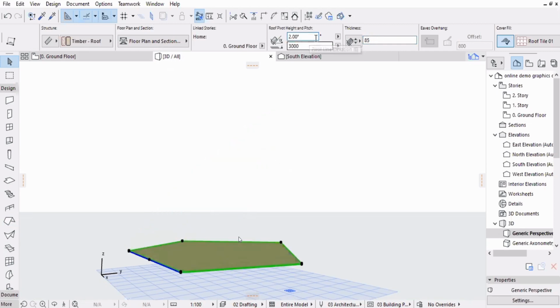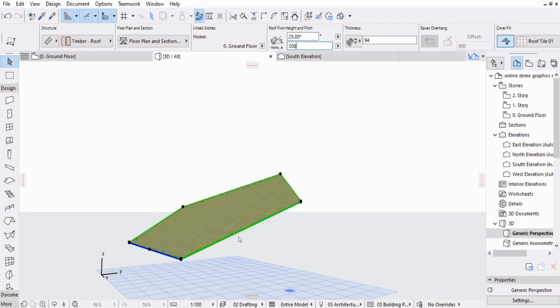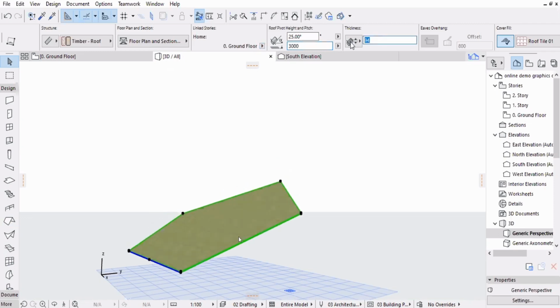You want to change the eaves height. Now, when you change this height, it will affect this pivot line. Essentially, this height is taken from the eaves. So eaves is this pivot line. Yeah, I can change it to 4 and see it's rising up, right? All right, I don't know how this changed.